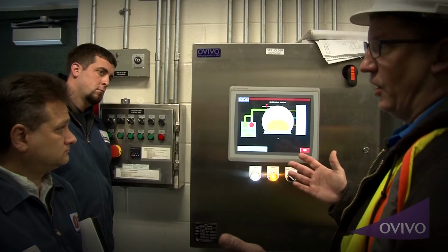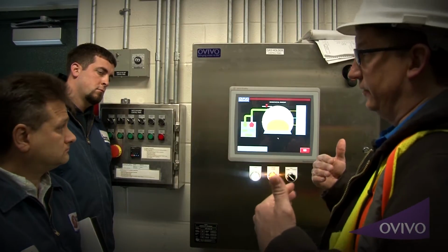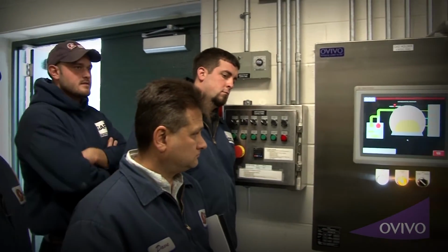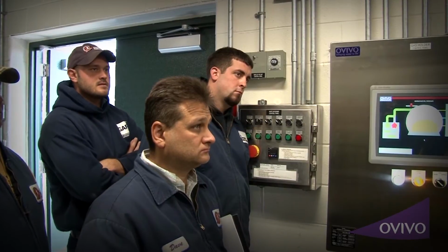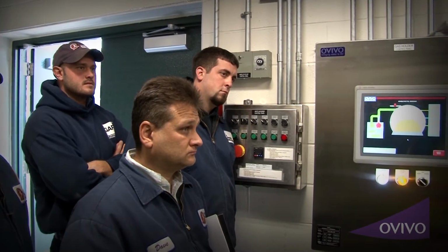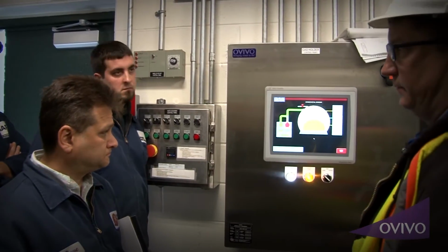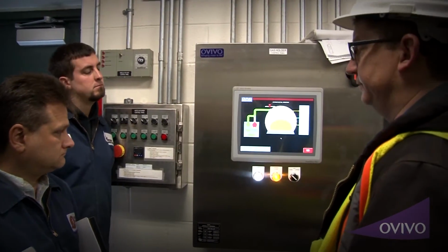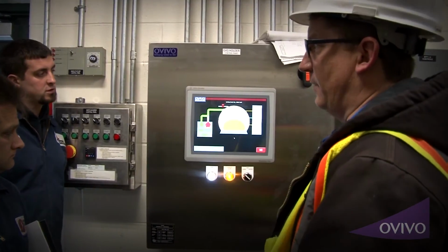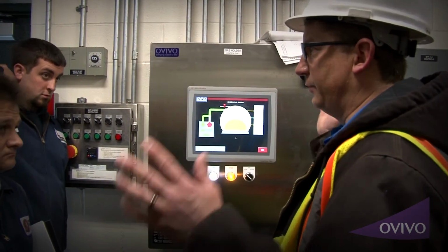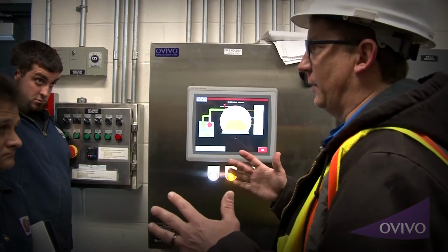That's a whole different scenario. But you guys start calling us. Emergency for us, just get on the phone with you guys? Emergency for you is to get rid of every ounce of gas out of there. Turn on your boilers, turn on your flares, and drain the whole thing out of gas as best you can, the safest way. And then at that point we'll leave it in purge mode, set up to where it's operating at the least amount of pressure possible.